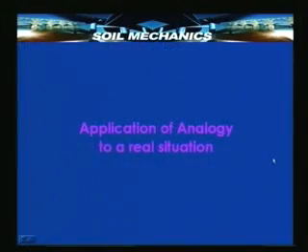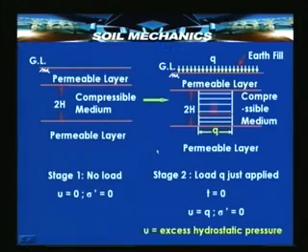Let us see the application of this analogy to a real situation in the field. See here, the first figure represents the real situation in the field, in which there is a compressible medium which is sandwiched between two permeable layers. That is stage 1. Now, there is no load, and that means, talking in terms of stresses, the excess hydrostatic pressure u is 0, and the effective stress sigma dash is also 0, because there is no stress applied and the soil is in equilibrium under whatever stress is there due to its own weight.